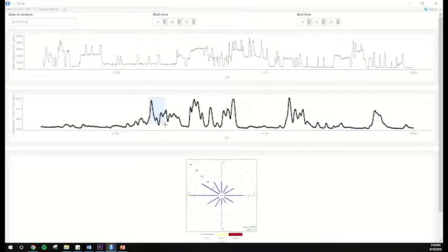Conversely, if we look at periods of time during which there is clearly an elevated signal of CO2, we see that nearly all of the wind is coming from the west as it blows the CO2-laden air towards our detection tower. This analysis indicates that we are in fact detecting the vent's emissions and that we can accurately predict the direction of the leak.